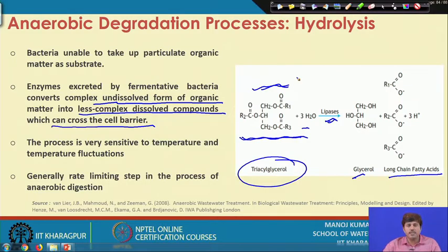So, this process of hydrolysis is very sensitive, and that too in the case of anaerobic degradation. Anaerobic hydrolysis is very sensitive to temperature and its fluctuation, okay, and that is why it is an essential step, because without this you are not going to produce compounds which can be taken up by the bacteria. So, that becomes an essential step, but it is highly sensitive to temperature and its fluctuation and some of the other parameters as well.